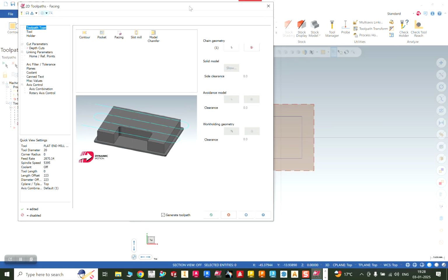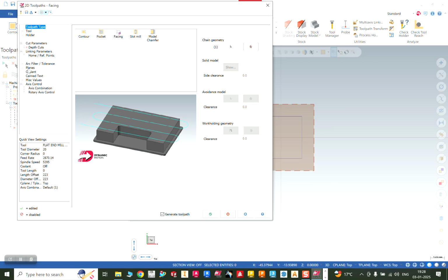After that you will see that the finishing operation window is going to open. Yes, sir. So the finishing operation is open. What we are going to do here, first of all, the important point is selection of the tool. In the tool path now you can see these are different types of operation it is showing. Now default facing is selected. And the chain I have given over there, you can give from here also. That selection can be done from here, but we have already done this tool path type in the previous operations.